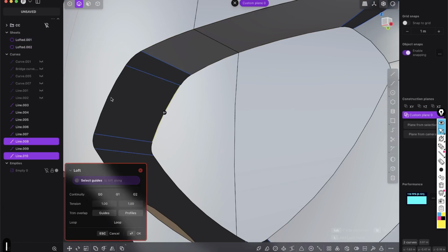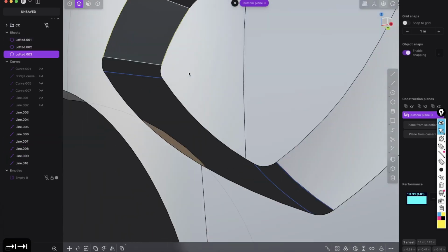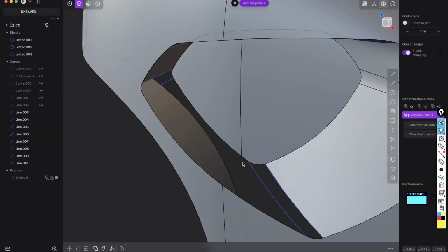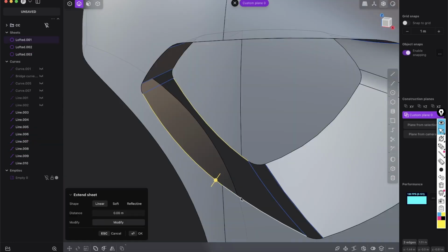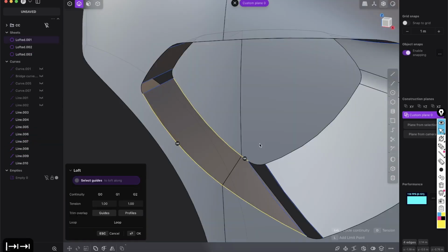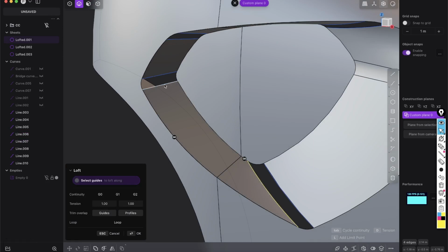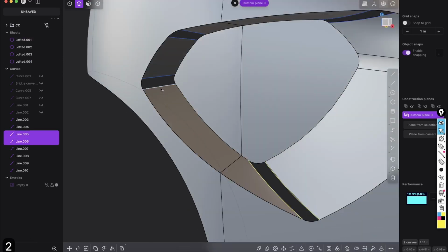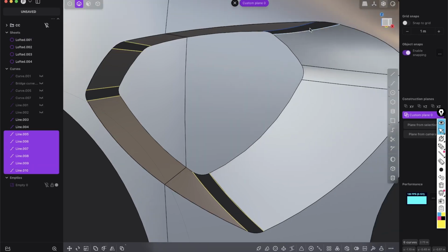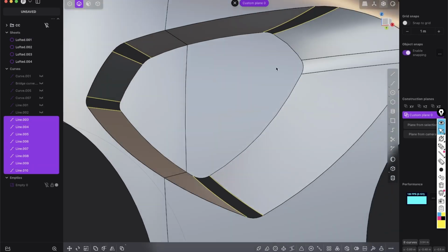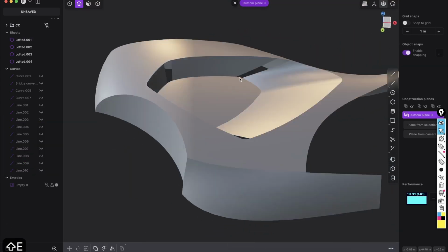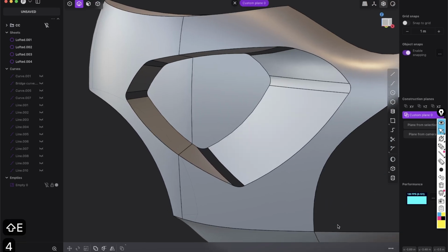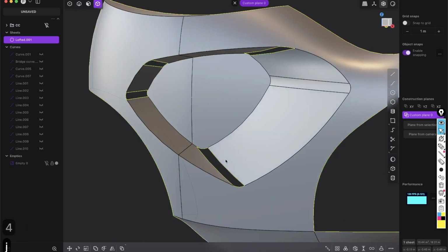And again, the long ones here with G0 and here as well. So select those and those. Here it might be trickier. So it's G0, but okay, it will work. And now delete or hide all of those curves here. So we can select the edges, and you see that looks already fine, and press 4 and join everything.